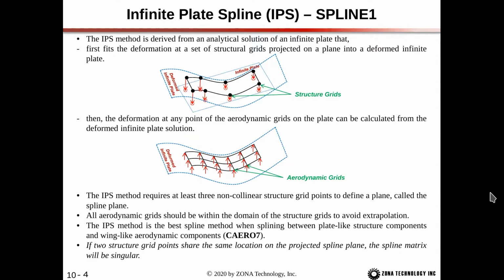So first, let's talk about the infinite plate spline, which is the Spline1. The infinite plate spline method is derived from an analytical solution of an infinite plate that first fits the deformation at a set of structural grid points projected on a plane into a deformed infinite plate. So if we have our structure grids here, first we take all of our grids, the original grid locations, and project those onto a plane, which is our spline plane. Then we see what the deformation is of each of those grids,